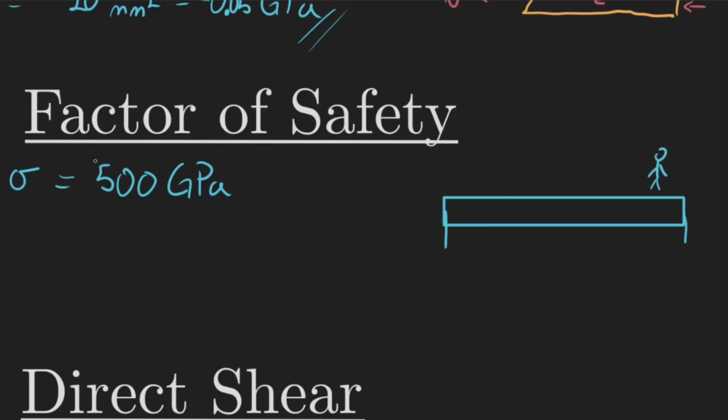What if it exceeds the weight limit slightly? What if there's some problem, stuff happens? We need some way to ensure that this isn't going to break on us. And one thing we could do is introduce a factor of safety. So for a bridge, usually a factor of safety is something like 5 to 7. We could just say, 3 seems good. Less than 1 means that your thing is broken. It should never be less than 1.